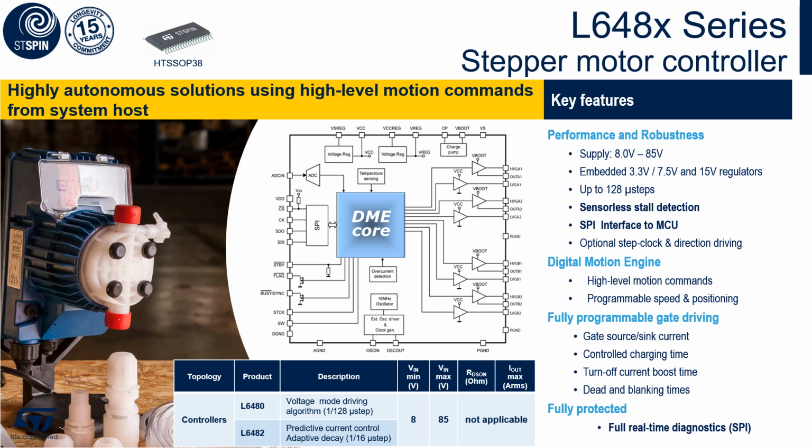The L648X series is an advanced and fully integrated bipolar stepper motor controller with microstepping. It integrates a dual full bridge gate driver for N-channel MOSFET with a non-dissipative overcurrent protection. The controller works from 8 up to 85 volt with adjustable gate current and a charge pump to supply the high side. It has two embedded voltage regulators, one for the control core and one for the driving section. It offers an SPI interface to the microcontroller, sensor stall detection, and a digital motion engine core for programmable speed positioning and many more features.